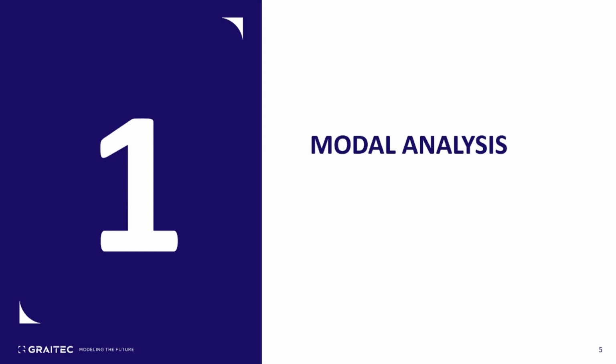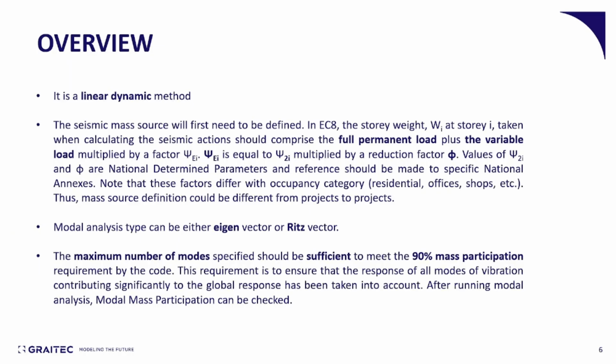Let's start with modal analysis. It's a linear dynamic method. Although we use the term dynamic, the results we get are not time-dependent functions of the displacements. It's basically an eigenvalue problem as we know them from buckling, for example. The whole point is to define the seismic mass, which is basically the amount of mass that is going to be excited, and there are different rules in the Eurocode to do so.